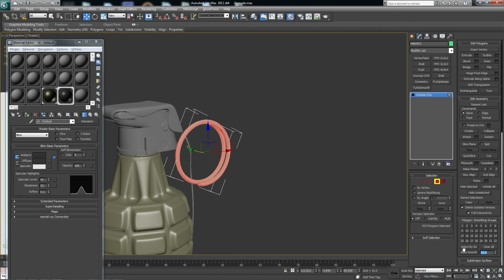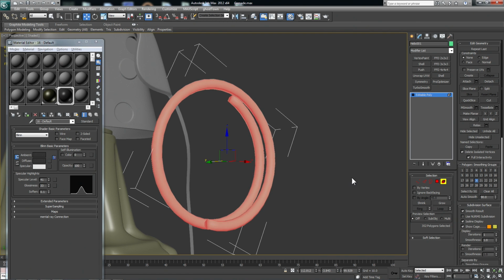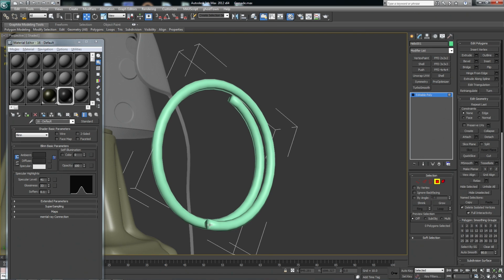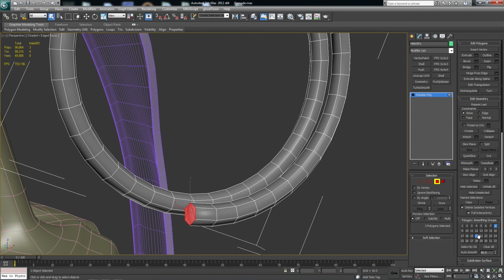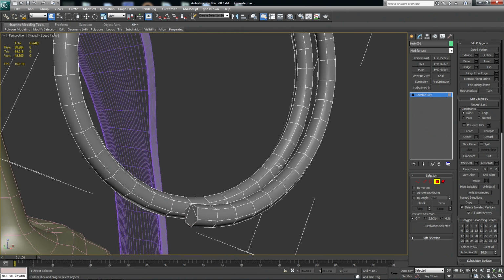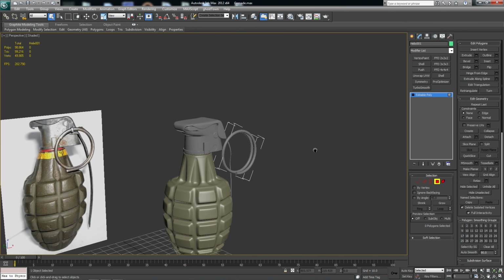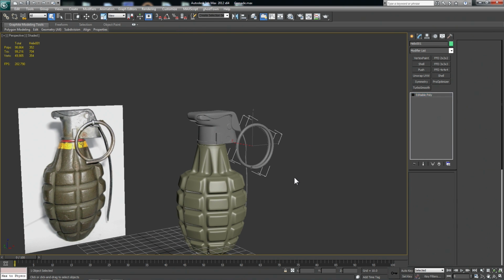Choose an unused group to assign all of these faces to one smoothing group, which creates a nice soft shading. Now this looks pretty good except for the end pieces, so let's select these as well and give them their own group and then deselect the previous group. Okay, now you get a nice hard edge on the end and smooth around the coil.